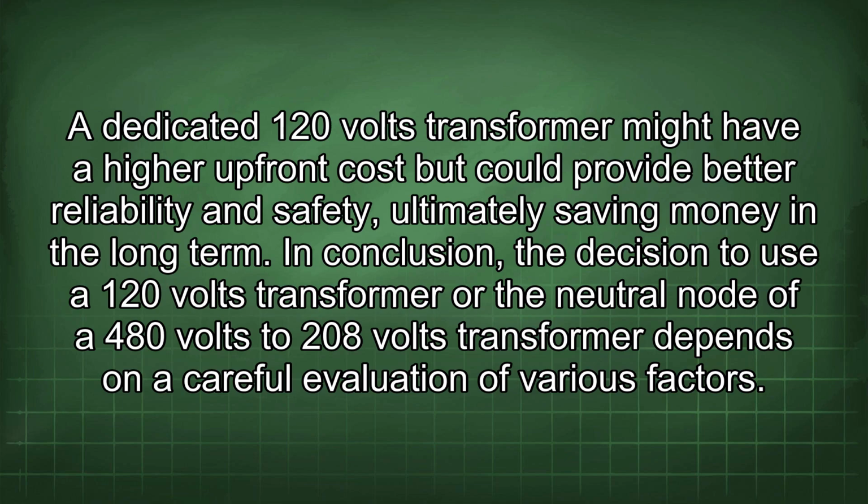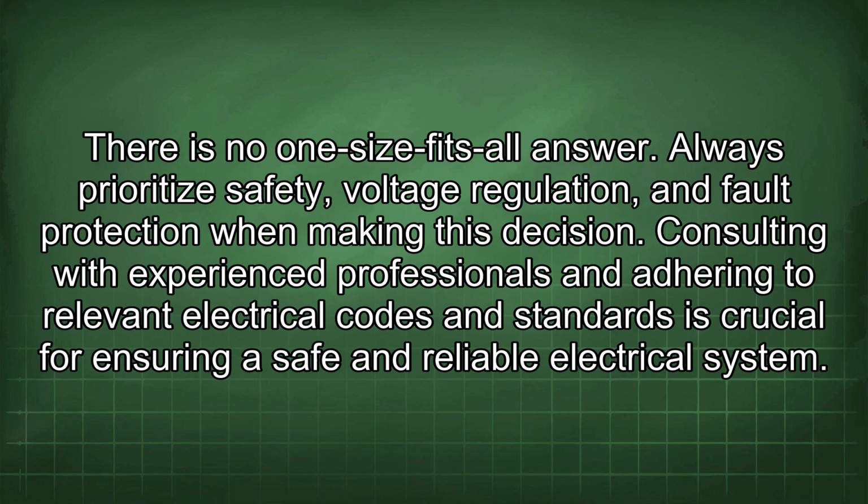In conclusion, the decision to use a 120 volts transformer or the neutral node of a 480 volts to 208 volts transformer depends on a careful evaluation of various factors. There is no one-size-fits-all answer. Always prioritize safety, voltage regulation, and fault protection when making this decision. Consulting with experienced professionals and adhering to relevant electrical codes and standards is crucial for ensuring a safe and reliable electrical system.